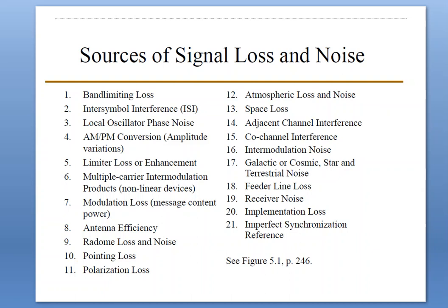And the next one, intermodulation noise. The IM products described here result from multi-carrier signals interacting in non-linear devices. Such IM products are sometimes called active intermods.